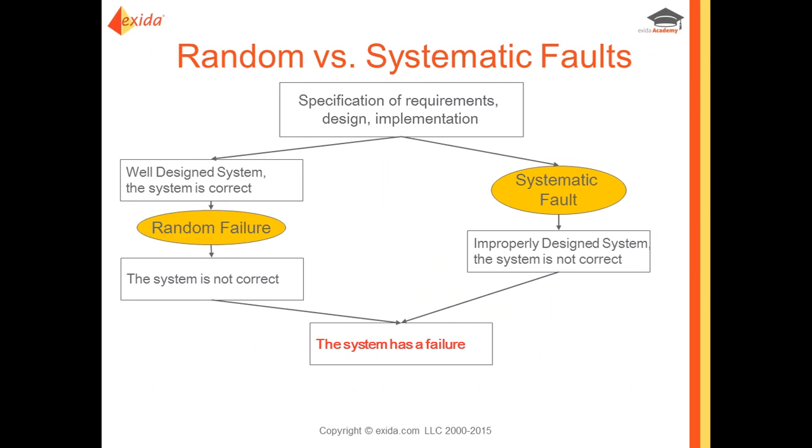As we talked about a little earlier, you look at 4 main things to determine the PFD average: the dangerous undetected failure rates, which you receive from the FMEDA, the proof test coverage, the proof test interval, and the mission time. And these are all factors in the equation below.